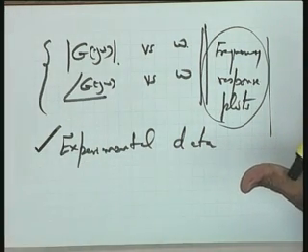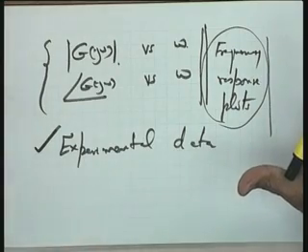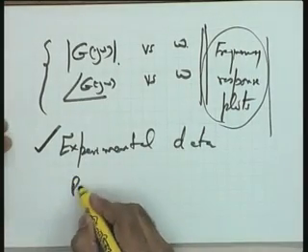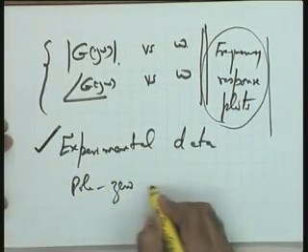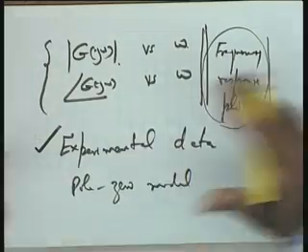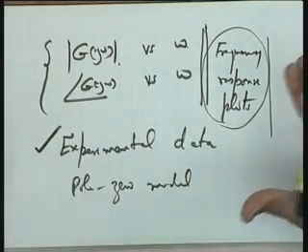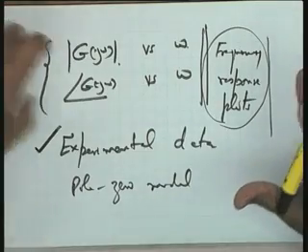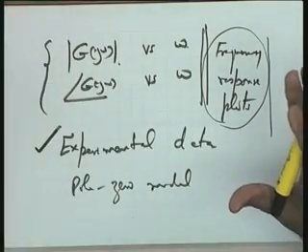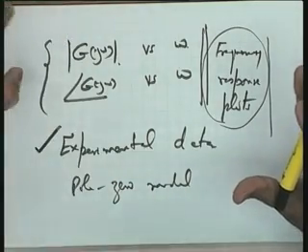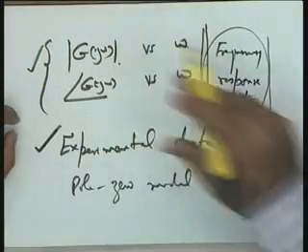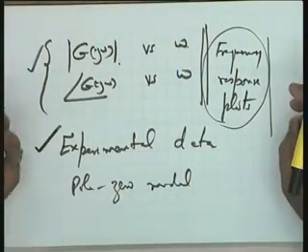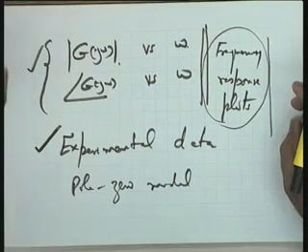Please see, you will have to first identify the mathematical model of the system, and the mathematical model is nothing but the pole-zero model, which is nothing but the transfer function model of the system. But if you go for the frequency domain formalism, if you are given the model obtained by physical laws or by any other method, you can obtain the frequency response this way, or equivalently you subject your system to sinusoidal testing, and sinusoidal testing is easy hardware-wise also.